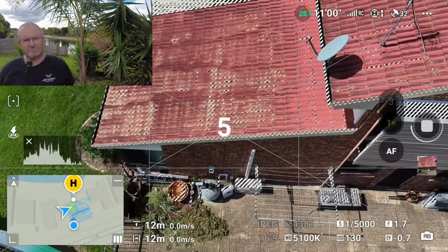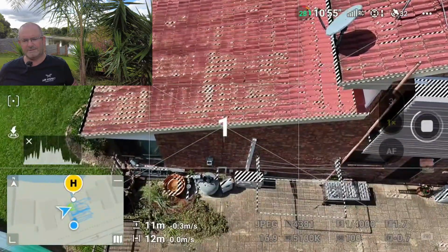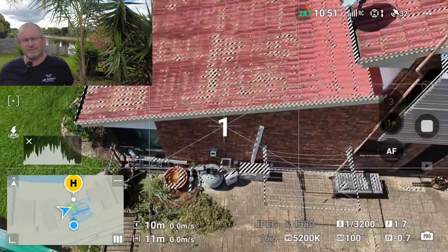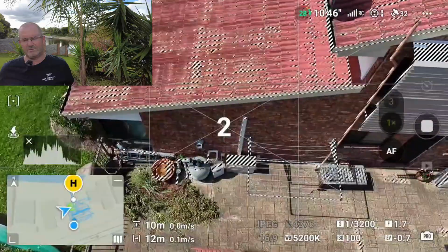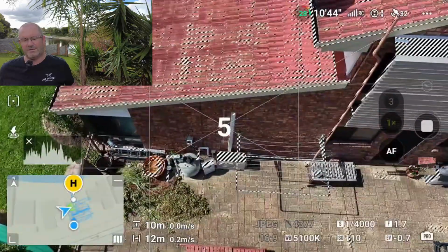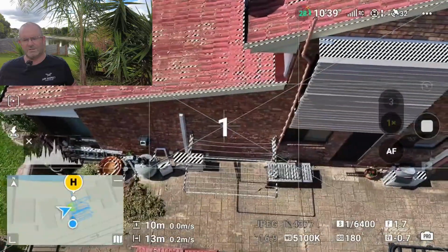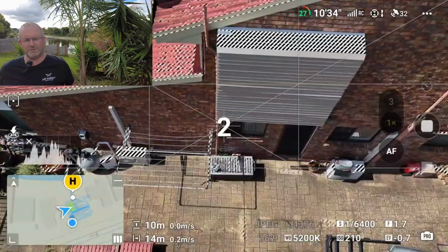But if you've got a building that you're doing, a warehouse that could be 20, 30, 40 meters tall, you want to be able to tie in back to the roof. If you can't, then you need to keep that in mind as you drop the drone without pulling back. And another technique we use is actually walking the drone. So you get the bottom of the wall tied in with the rest of the building.